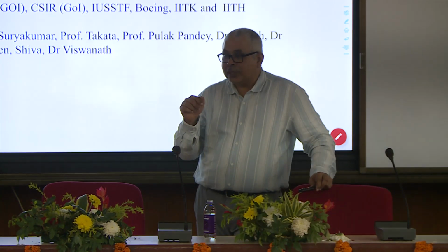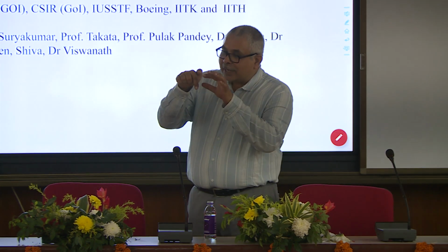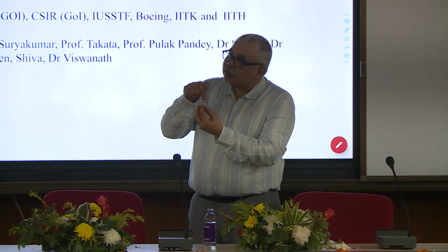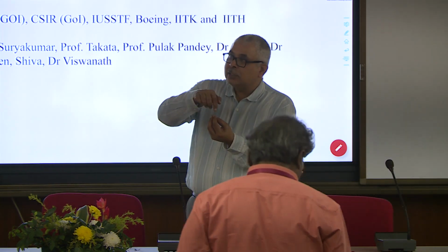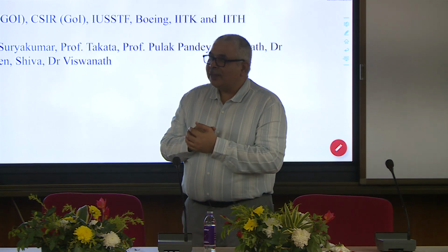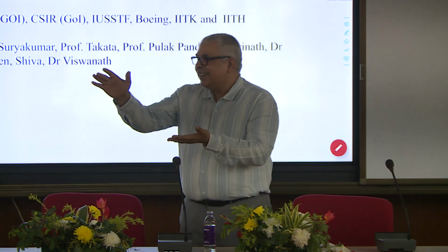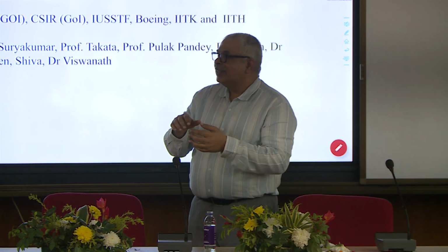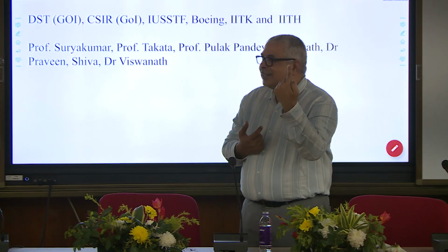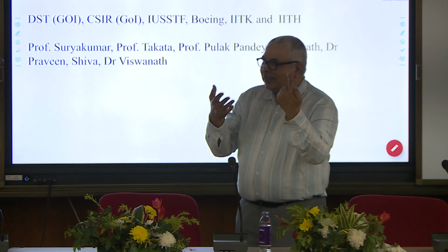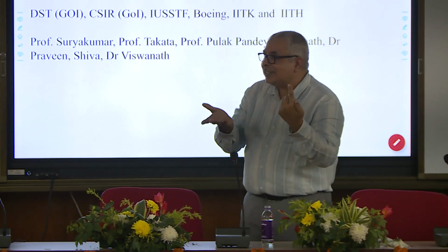But the moment you go there, whether it is laser deposition or arc deposition, a variety of forces will act around the deposited bead. When my torch is at different angles, the bead profile is different. Even if I consider the layer as a uniform layer, the torch orientation has to change from instant to instant depending on the local geometric conditions, the surface normal.